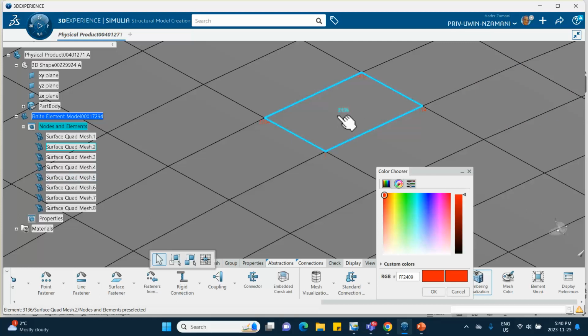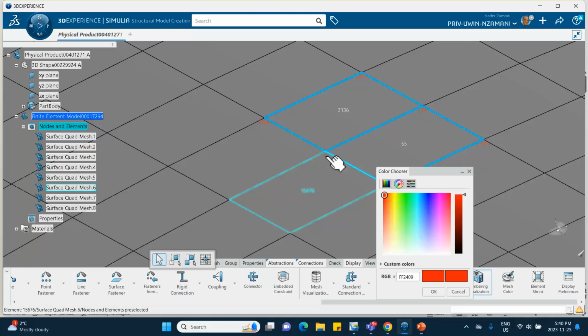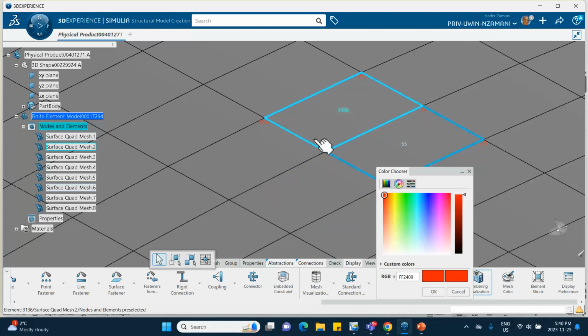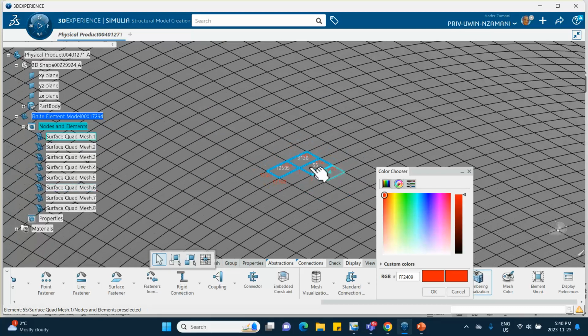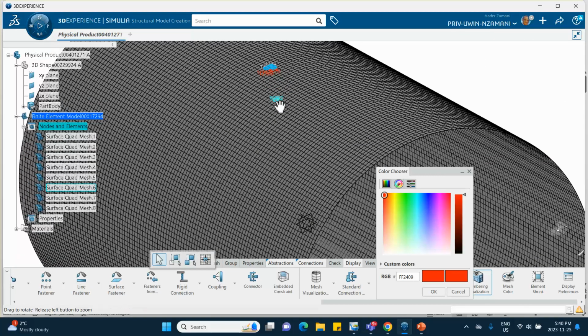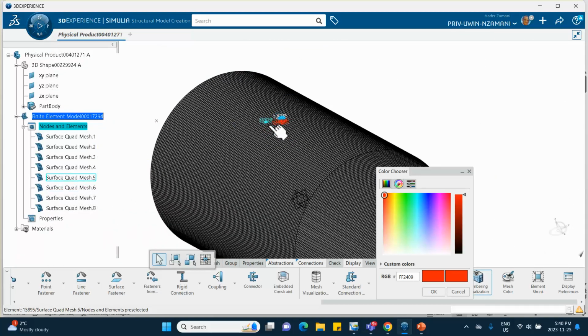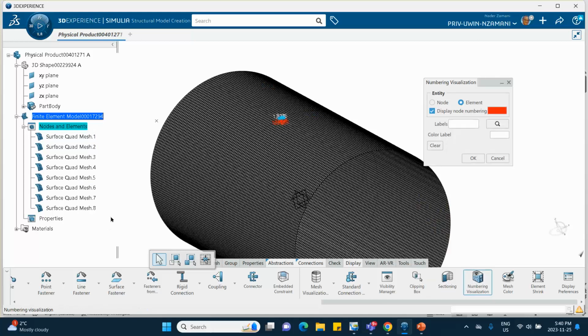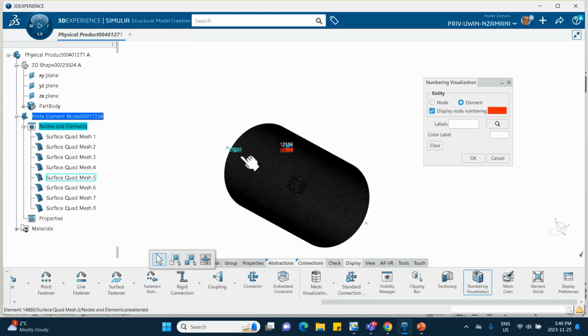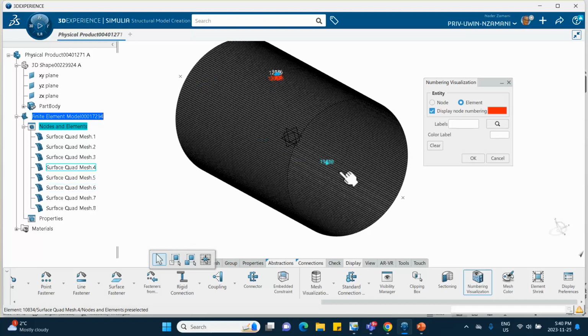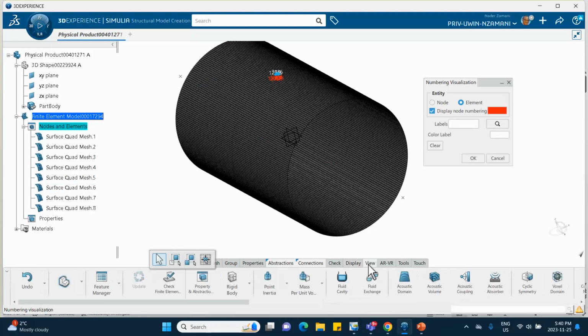So this one, notice that there's a node number 1 here. I can see that. If you select the other one, it's also going to be node number 1. There is nothing overwritten on that node number 1. If you had not merged the mesh the way I suggested, then there would have been a duplicate node at that location. Okay, good. So I'm done with this. Let me put this in a view that I can easily see.